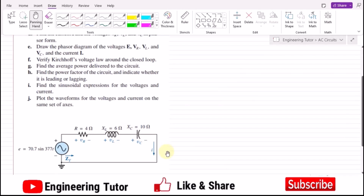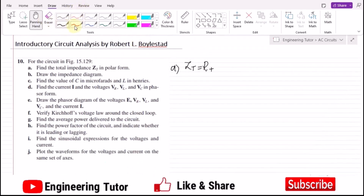So that is a very conventional RLC circuit. We have to write the values of XL and XC here, and we have previously seen that in order to write the value of XL we have to put a plus j with it, while with XC I have to write a minus j. So writing them here as imaginary components, j XL, and similarly XC. Now putting their values, what will I get?